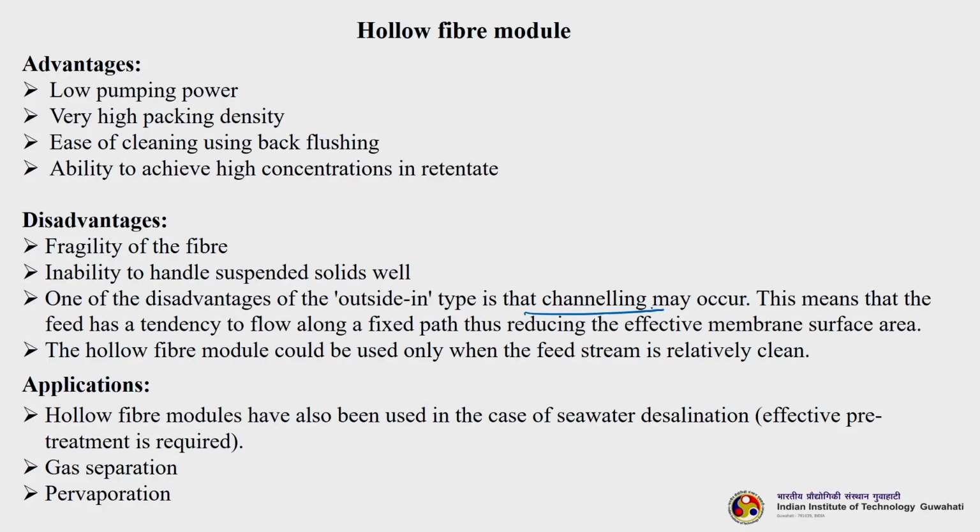Channeling is something which is very much inherent to packed bed type reactors. The same thing may happen here if you are using an outside to in system. This means that the feed has a tendency to flow along a fixed path, thus reducing the effective membrane surface area. So, if we want the entire membrane surface available inside the module to be utilized, then it is better to take the feed and flow it through the membrane.